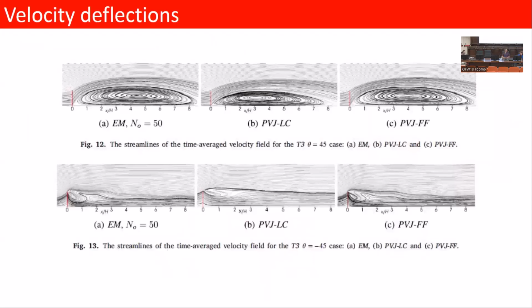So this is the result. The left column is lamellae, many lamella, like 50 lamellae. You don't see them because they're very small, but there are 50 lamella explicitly modeled in OpenFOAM. I need to warn you, these are 2D URANS, but still, we needed to make 50 lamellae to deflect the flow exactly in the direction we wanted. In the top row, they are pointing up, and in the lower row, they are pointing down. And you see that this has a dramatic effect, of course, on the flow that is created downstream of the barrier.